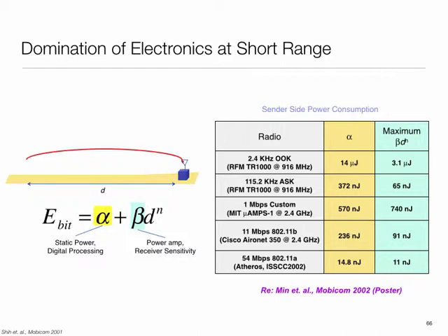Let's take something like, I mentioned ZigBee radios earlier on. In the case of ZigBee radios, my payload is relatively small, but the header is relatively huge. So you might have this situation where, let's say I have a sensor which is sending a temperature reading, maybe a couple of bytes, but the header itself might be 32 bytes or something like that. I think in ZigBee it is something like that. Okay, so just to send a couple of bits every so often, I'm actually sending 10-15 times more bits for the header part of it.